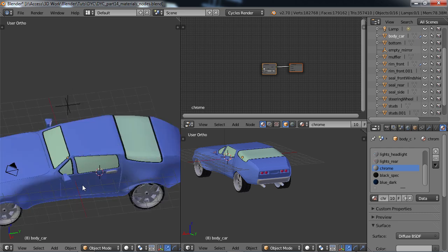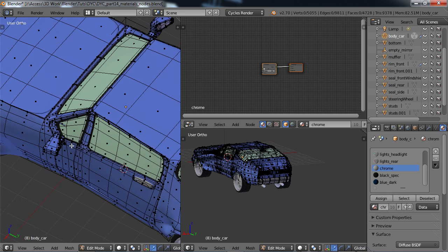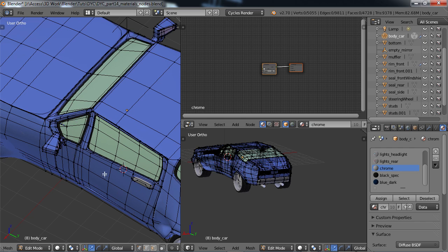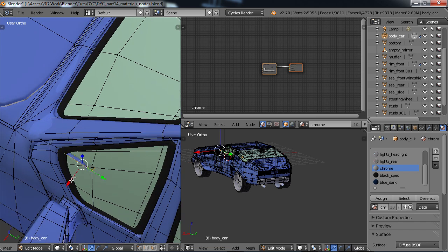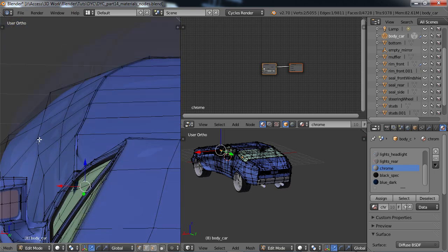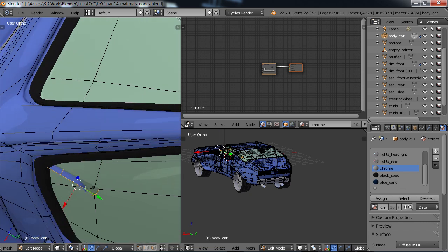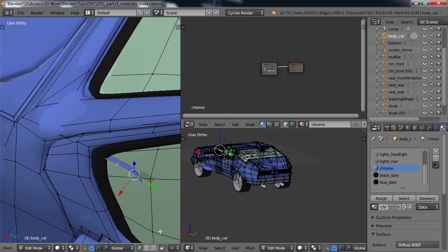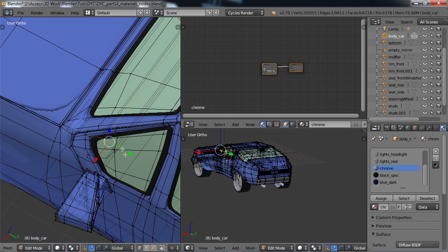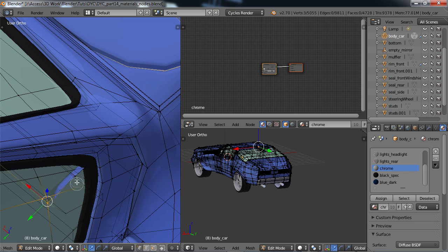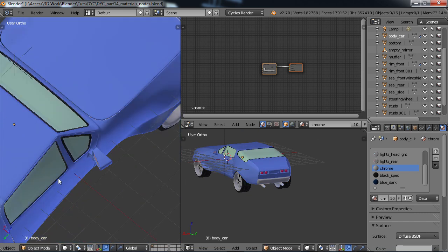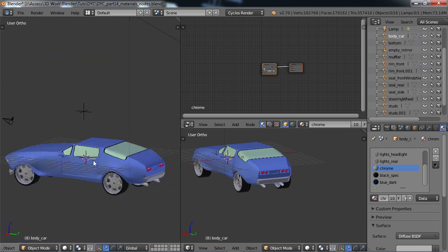Another thing I needed to do, I think, is select this. Let's go to Vertex Select, Z. That's very hard to see. I need to get this stuff out of the way here. What's going on there? More than one vertex there, I guess. Okay, just bring that in a little bit, and same thing on the other side. Okay. So that's the tag, that is the handle,